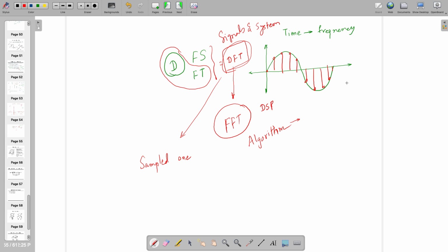It is not happening at all. So what you are doing is taking a small photograph, and for that photograph I am going to take the Fourier transform or Fourier series. This signal is continuously coming, but I am doing it for a fixed photograph. Technically, you can call this photograph a window.